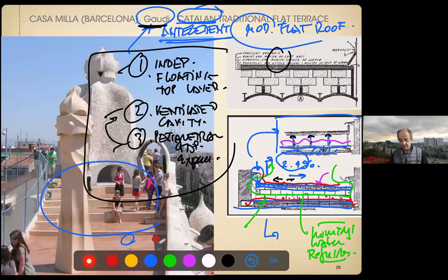But even if you don't have this final layer, you may also have some waterproofing in that part, depending on how you do it, and depending how long it rains, right? But yes, one of the strategies all the guys use in flat roofs is to increase the slope a little bit, so the water doesn't have time to filter down.